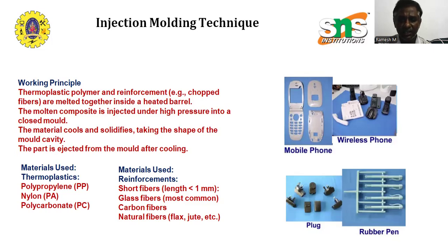In the side gate, the design is two plate. The plastic must flow around the core and join on the opposite side, possibly creating a weakness at the weld line. Secondly, the three-plate mold allows more automatic operation of the molding machine. As the mold opens, the three plates separate. This forces the runner away from the parts, which it drops by gravity or using an air blower into the collecting containers put under the mold.